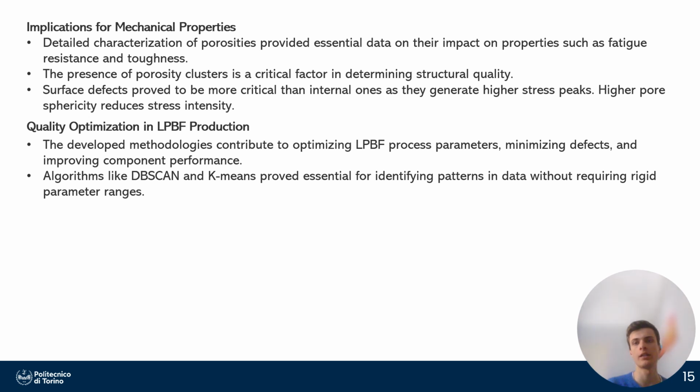The detailed characterization of the pores has also provided crucial insight into their impact on key mechanical properties such as fatigue resistance. Indeed, porosity clusters play a critical role in determining the structural integrity of a component. Among the defects analyzed, surface defects were found to be more detrimental than internal ones, as they induce higher stress concentration.